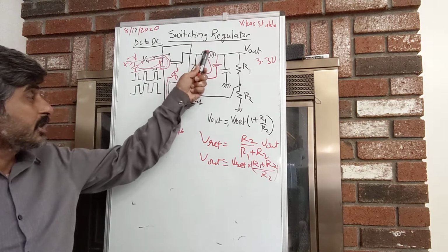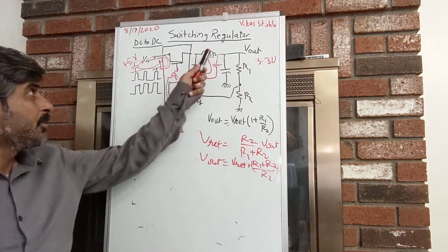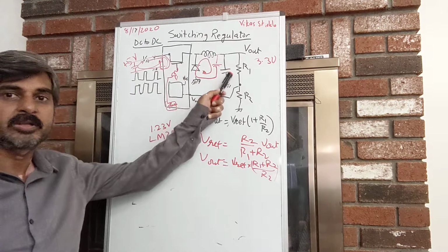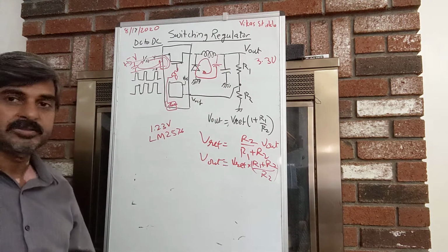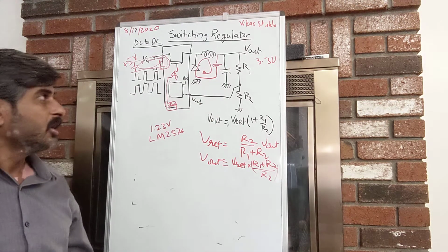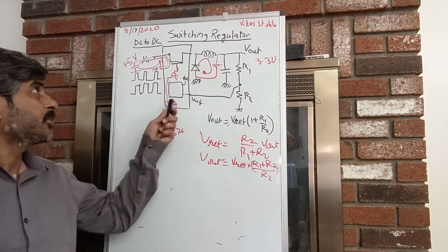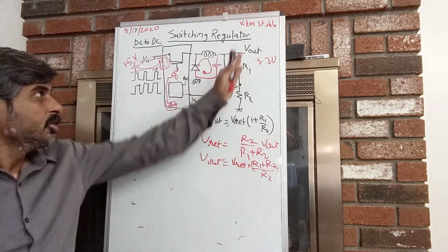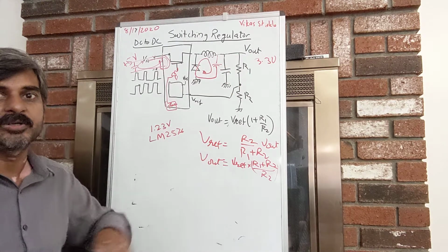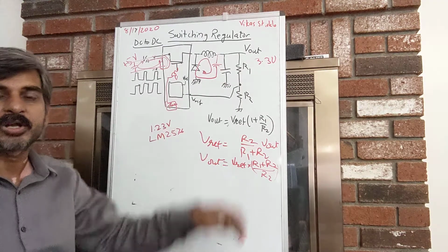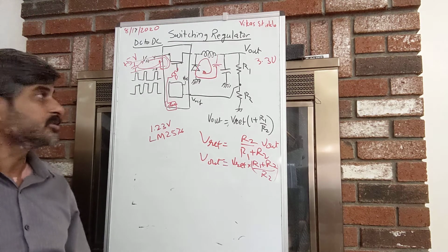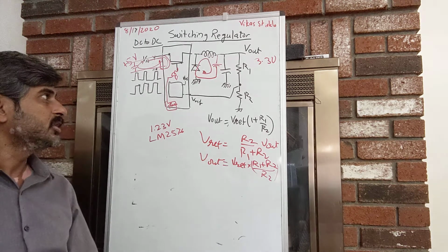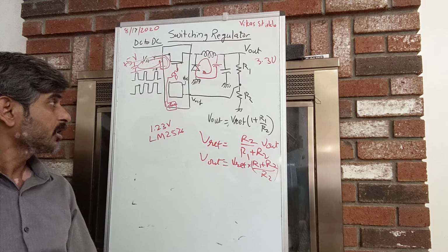There is other consideration, for example, the calculation of this inductor and the capacitor that is required, which will depend upon the switching regulator itself. In addition to all these things, you need to have bypass capacitors and the layout for the whole circuitry. For example, if this switching regulator is providing supply to your CPU, you need to take care of these things.